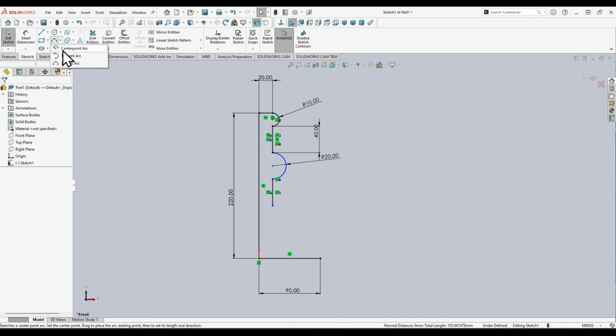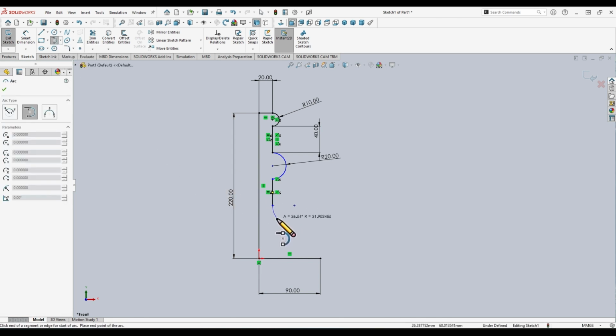So then it wants me to use the tangent arc tool to draw an arc coming this way. And this one, when we draw it, we do want the piece of pie, the nice 90-degree cut here. It doesn't really matter the radius. We're going to end up dimensioning it for 60 millimeters, but it could be some arbitrary radius right now. The important part is the A equals 90 degrees. We want this to be a 90-degree drawing right here. So I'm going to click there. And I'm still in this arc tool, so I'm just going to finish the drawing by coming down to this line and making sure that little point turns orange, and I'm going to left click on that. So now I'm done with the drawing, and I just have to finish dimensioning things. So I'm done with the arc. I hit my little check mark.